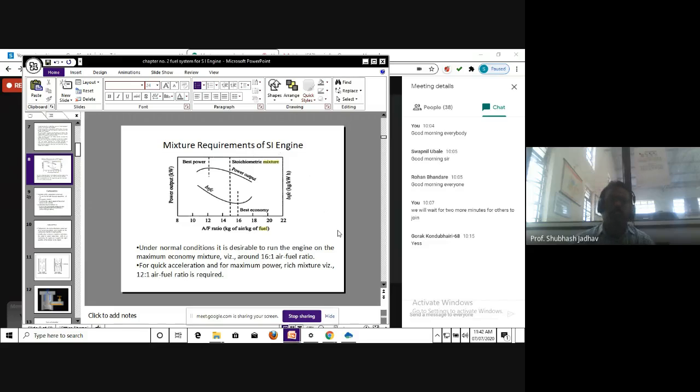And obviously, how we have designed the carburetor. Because this particular process of formation of the combustible mixture is happening inside the carburetor, how we have designed the carburetor is also going to affect it. So these many parameters we need to keep in mind when we are thinking of a carburation process. So we said the carburation process is a process of preparing the combustible mixture as per the requirement of the engine before it is being supplied to the combustion chamber.